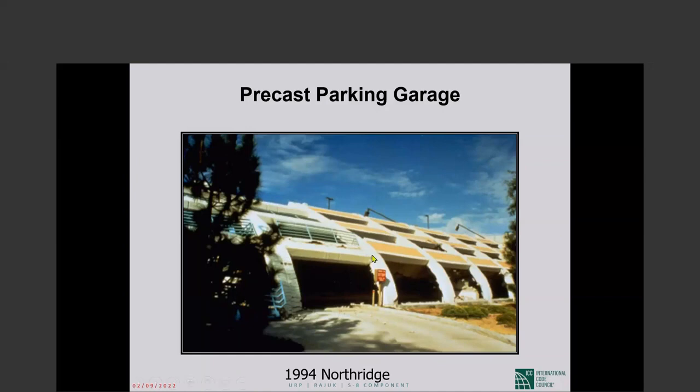Here in the earthquake, for reasons I won't go into, the special moment frames underwent out-of-plane displacements of several feet. And look at the frame. It has cracked, but that's about all that has happened. No piece has flown. I don't want to say the frame is in good shape, but it has definitely held together admirably.